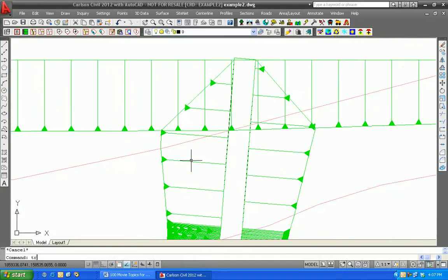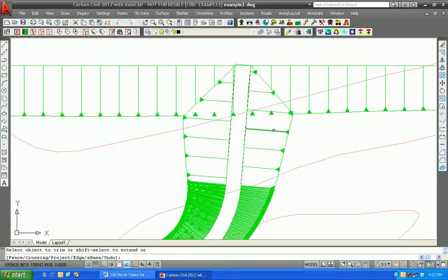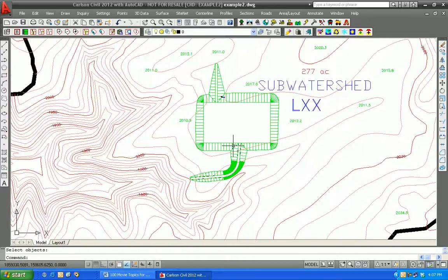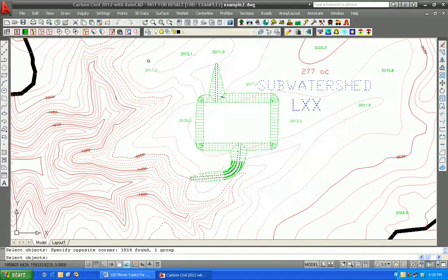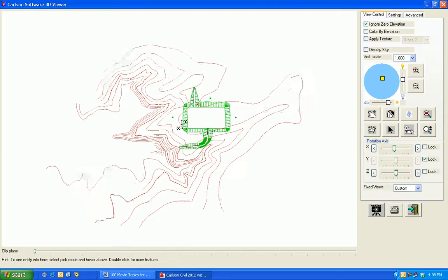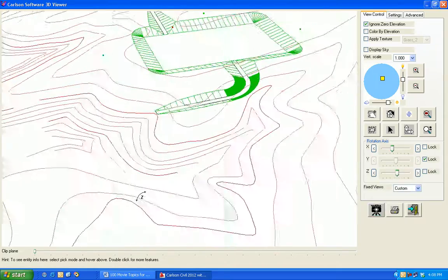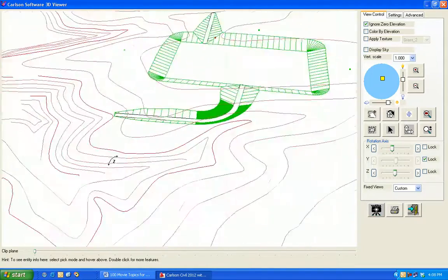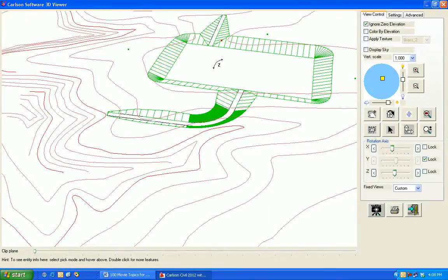But we can quickly go through the trimming process after the fact using that trim perimeter and selecting the pieces from the original design as shown there. And then we can also erase some of the remnant slope direction arrows and pretty much result in the final look. Let's verify it in the 3D viewer window. Come in and select a few of the original contours and our various ramps, and you can see how this looks versus the original ramp that we did.